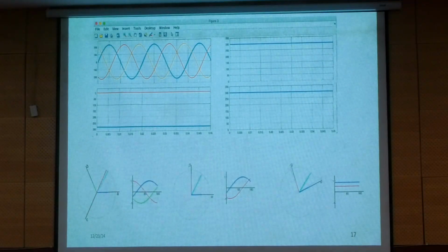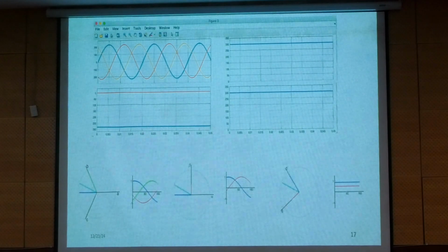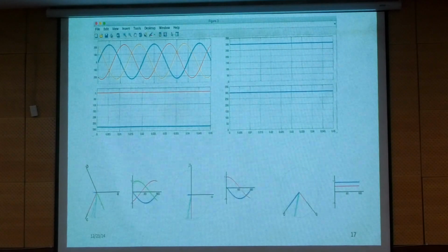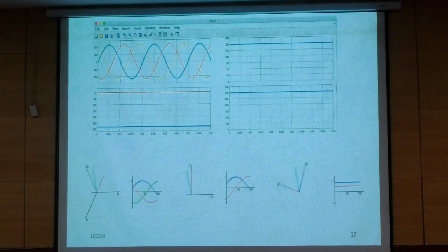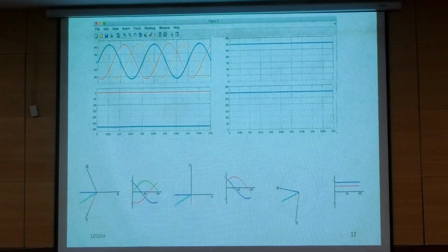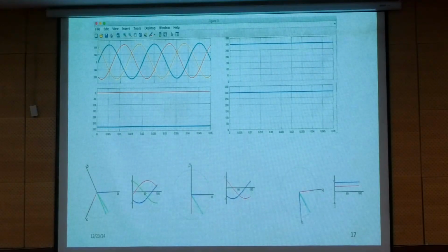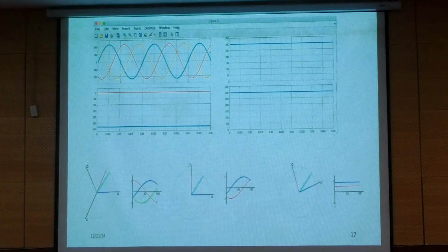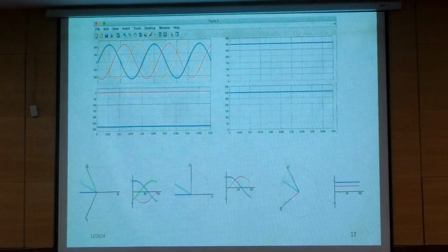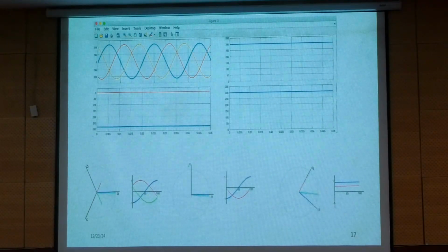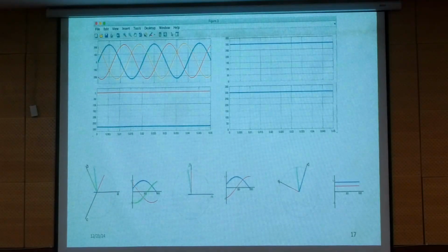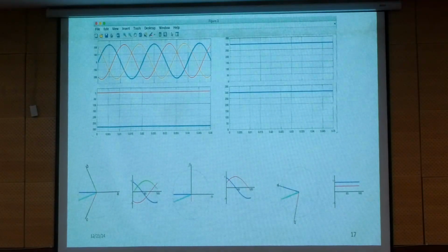By using FOC theta we are inducing it in the transformation technique, so that the system order equation will become from fourth order to second order. FOC is nothing but a combination of transformation, field orientation and V by F. There are 3 logics required. If you want to change the characteristics of the induction motor from 7th order to 1st order, you need to take 3 concepts.